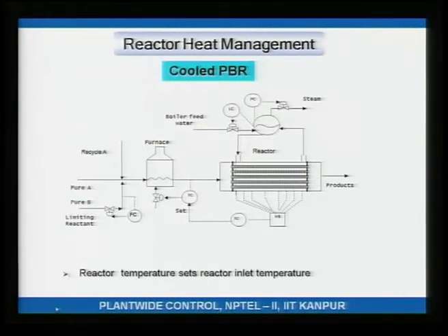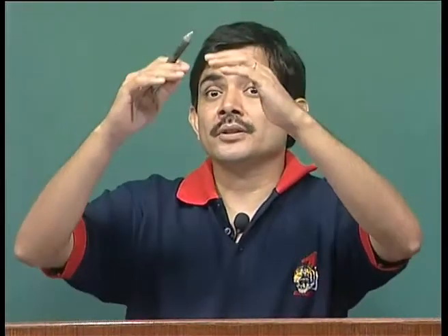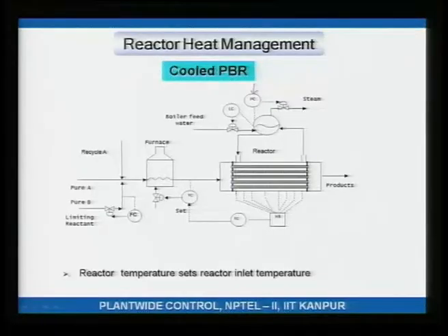Now, let us say I have here a different scheme. I will hold this pressure set point constant, I will not manipulate it. Instead, I will reduce the temperature of the inlet. Because the temperature is getting reduced, reaction rate in the initial parts will get reduced, therefore, the amount of heat that gets generated gets reduced, therefore, the hotspot temperature that was going up comes back down, and vice versa. This scheme, even though it is conceptually feasible, is not recommended in practice, and the reason for that is as follows.